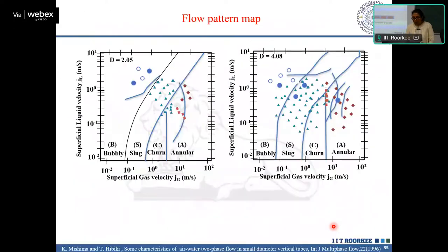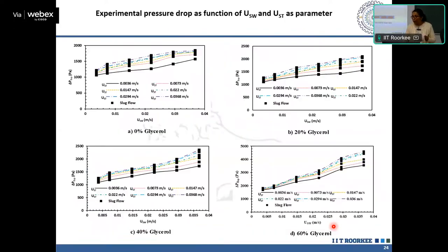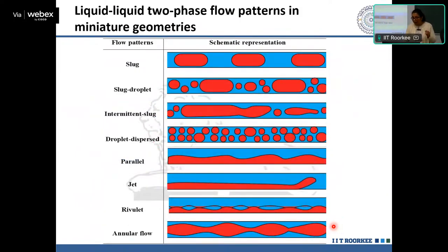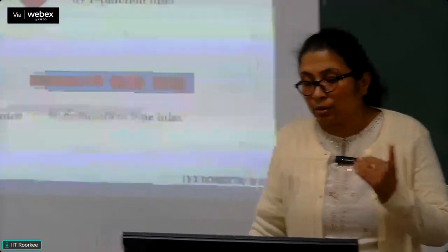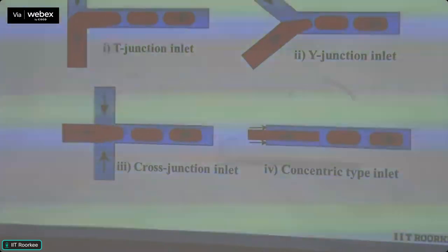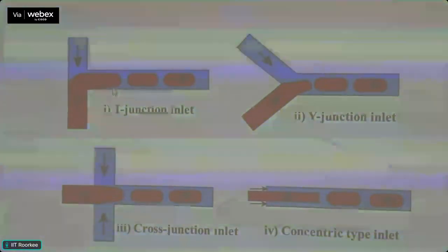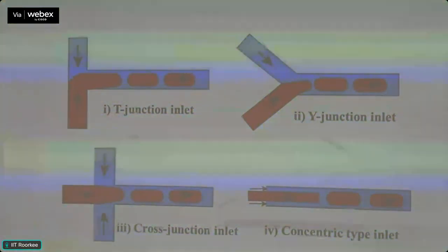Okay, so something like this kind of injection pattern can give rise to that parallel flow. They are introduced like this with higher velocity of this particular liquid phase, forming a long jet over the channel, and that is what we call jetting. With a further increase in this phase, the two fluids are flowing simultaneously, having some kind of parallel distribution, co-flowing.